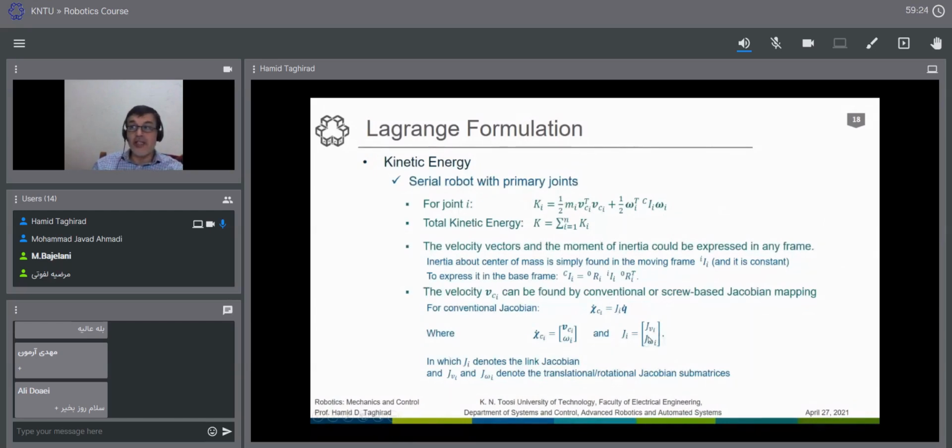And you know that this was the screw axis, exactly what we can find as the basis at the point on the screw. But the point of interest is not the end effector or the wrist, it is the center of mass of each link. So we do the same treatment as we did there, but for the center of mass. They are exactly the same as before, but we have an index i here. The subscript i represents each link.